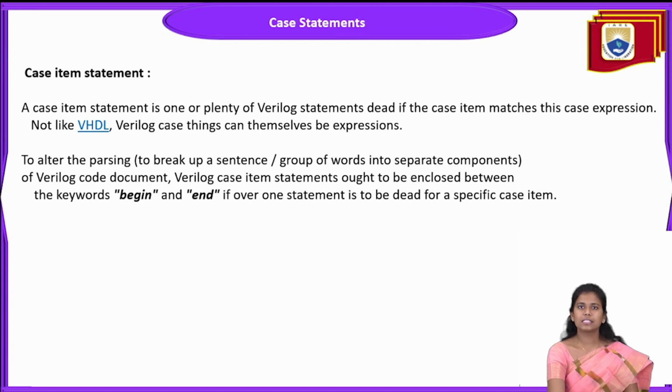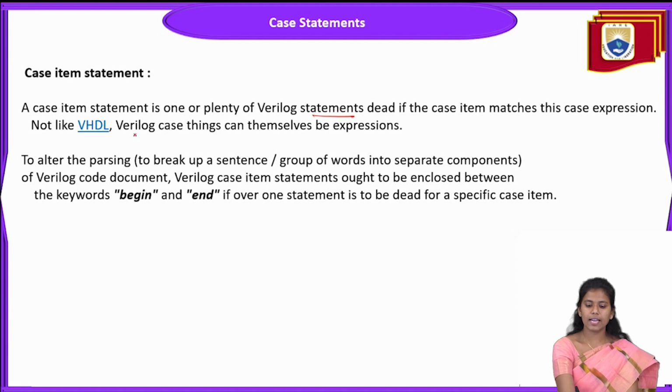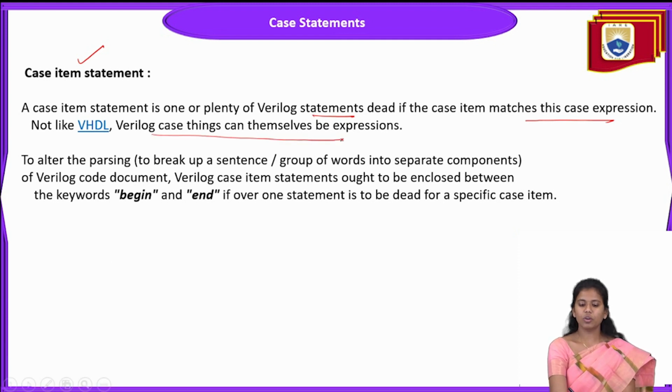And coming to the case item statement. So what is this case item statement? A case item statement is one or plenty of Verilog statements that execute if the case item matches the case expression. Not like VHDL, Verilog case items can themselves be expressions. It could be one or more than one Verilog statements.